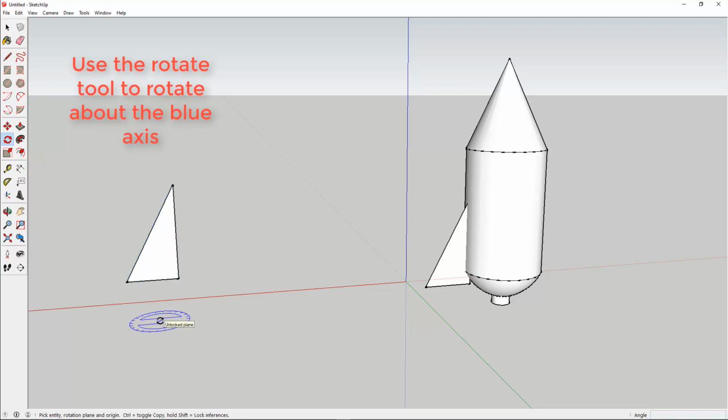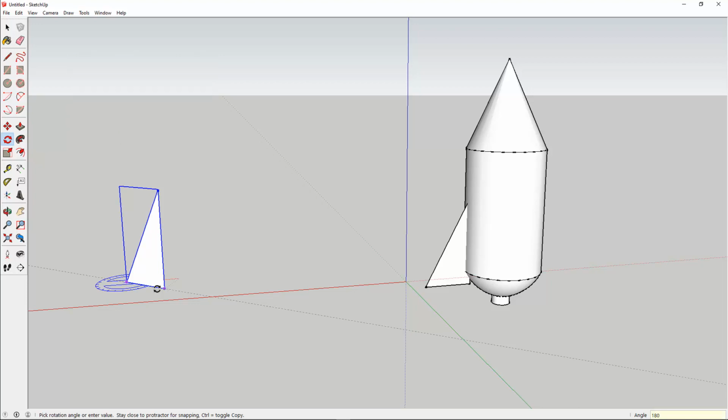So you move it around. There's the blue protractor. It's got to be, there you go. Click, go to the far side. Click, and I'm going to rotate it 90. If you have 3 of them, you're going to rotate it 60. Four of them would be 45 degrees.